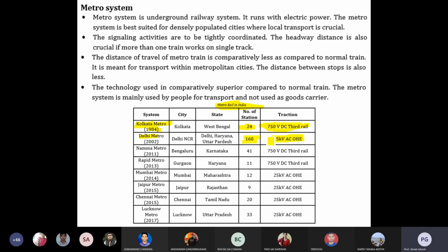For cost minimization. But the problem is that in the third line, if it is 25 kV, your ground potential is 0. So the difference between 25 kV and 0 is a huge potential difference, instead of 750 volt to 0 volt. I hope all of you are getting my point. That's why for underground service the normal consideration is 750 volt, so the insulation will be less and you can provide proper insulation in a cost efficient manner. That's the motivation.